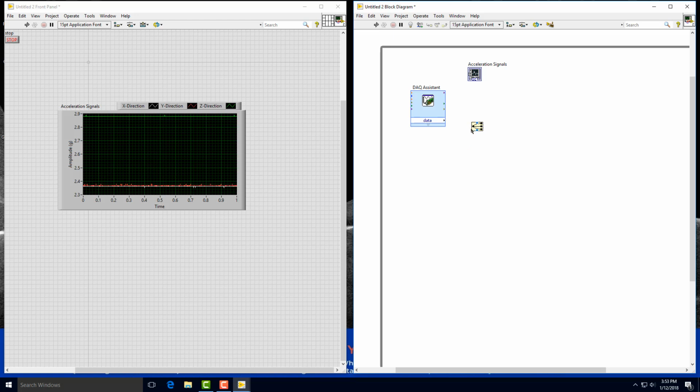On the left side, you are getting one signal in, and then it separates to 3 channels. The program knows that the first channel will be your channel 0, the second one will be channel 1, and then the third one is going to be channel number 2. So this will be X, Y, and Z going from top to bottom, okay? So all I'm going to do now is wire my data stream into the splitter, and now I have access to X, Y, and Z channels separately.